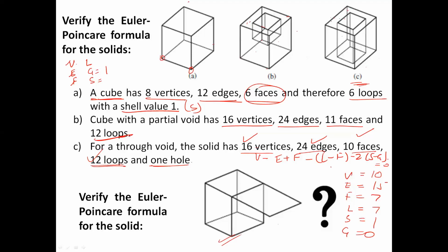The validity of the CAD model is basically defined by the 6 basic principles that we defined earlier, where we are looking into boundary determinism, homogeneity, three-dimensionality, non-self-intersection, and no additional loops or additional features extending out of the body without closure.